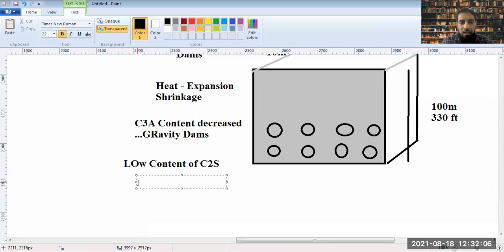So the rapidly hydrating content of C2S and C3S are both conserved. So you are then actually increasing the C3S. Some amount of hardening may be achieved quickly, but decreasing C2S at the same time, the hardening stage would not be such early. So you would have lower or slower development of the strength finally, because C2S is getting decreased.